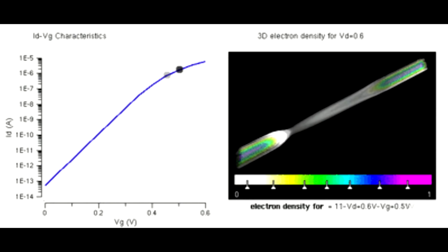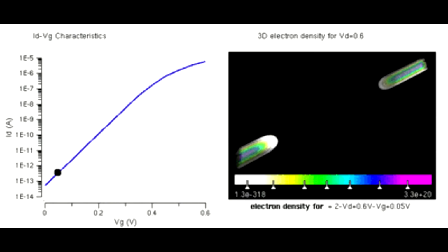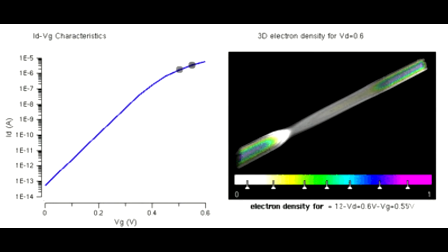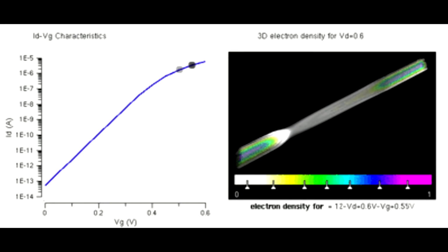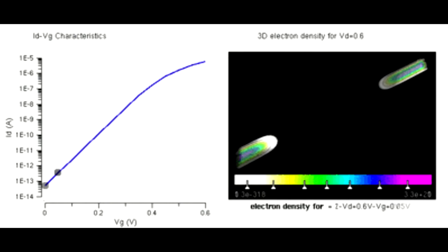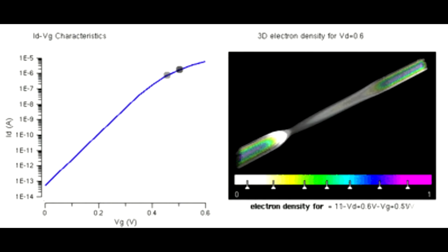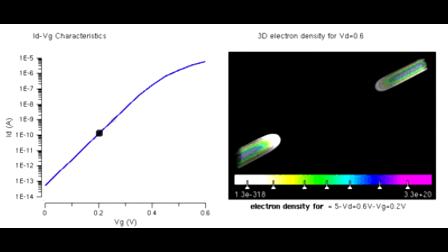And you see, as it goes up and reaches a threshold voltage, in this case of about 0.45 volts or thereabouts. This is a real low gate threshold voltage nanowire MOSFET, it's called. And you can see the electron channel then just sort of bang, there it goes. Fantastic. And of course, you keep increasing the gate voltage, as I said, then your conduction channel gets wider and wider, and more electrons can flow, higher current.